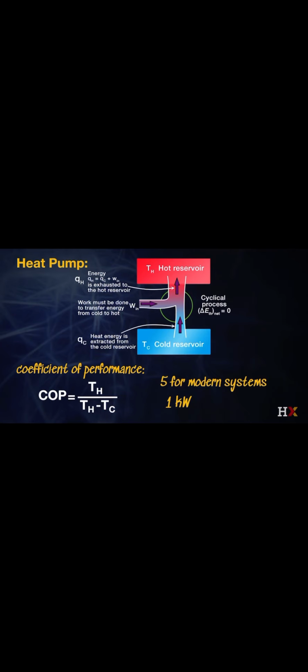At the same time we studied heat engines, we studied heat pumps, and we recognized that a heat pump has this profound capability called the coefficient of performance, which typically equals just about 5 for modern systems. That means that when we're heating or cooling our house or our building, 1 kilowatt hour of electrical energy coming in produces 5 kilowatt hours of energy for either heating or cooling.